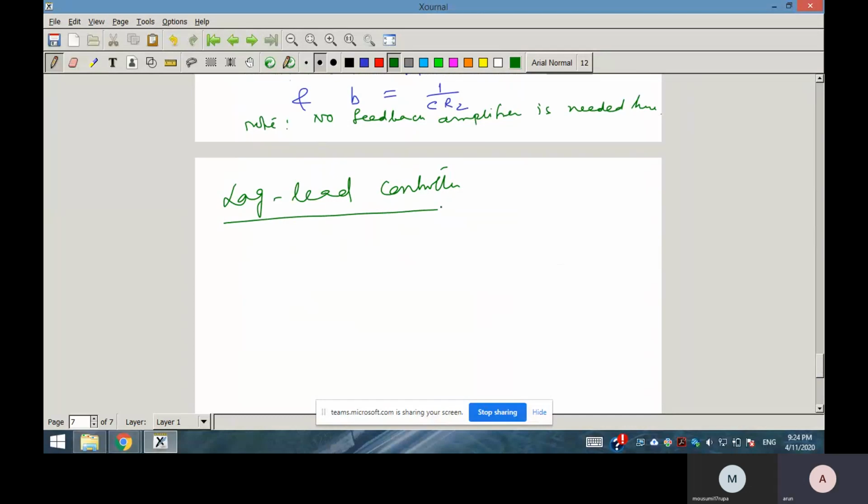We saw that the ultimate objective is to obtain a certain phase margin and gain crossover frequency using lead and lag controllers, because the steady state error specification will be met by the servo gain K. So using the normalized part of the controller, which we consider as HS, we want to obtain only two specifications, phase margin and gain crossover frequency. Using a lead compensator, the system will become very fast and the gain crossover frequency will increase, because it provides phase lead as well as gain amplification.